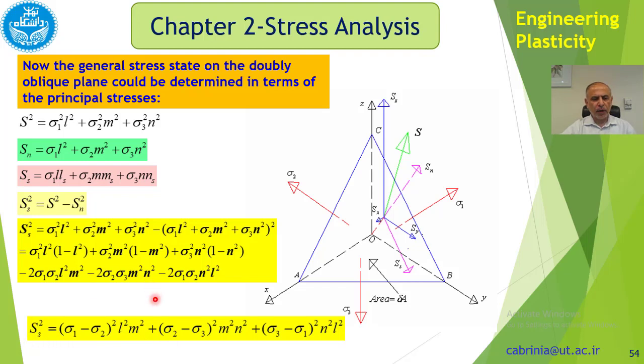And we have said before that the plastic deformation happens due to shear stresses only, because slip planes and slip directions are activated because of the shear stresses. If we don't have any shear stress, then we don't have any deformation. So once again here we can see that all these stresses, which are principal stresses, will cause this shear stress, which will cause the deformation, as we have said before.